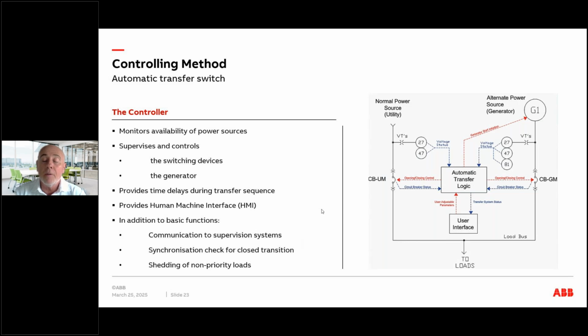So as we saw again with the example, when the generator came on, we stayed for a predetermined time, and again you can program the controllers now to be 10 minutes. The time delay or revert back to mains function is governed by what the client requires. I've known some cases where it's been 12 hours or more, and sometimes only once, by the way, it was 24 hours.